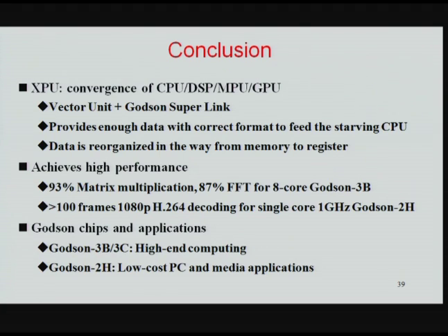So, conclusion. The XPU concept is a convergence of CPU, DSP, MPU, GPU. We try to put everything together. The key issue is that while we transfer data, in the way of calculation, we do data reorganization. And the data path is reconfigurable by the software.